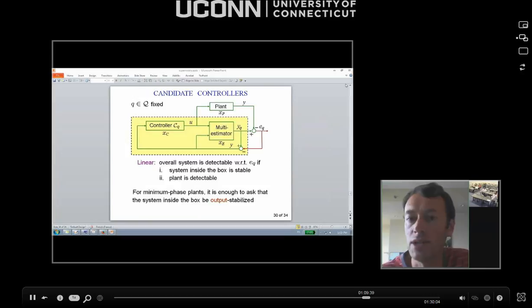And by the way, the detectability is not new, right? If you look at the papers by Steve Morris on adaptive control from the early 1980s, I think he called it tunability or something like that, but essentially detectability is known to be key for traditional adaptive control. So we're not saying anything new in that regard. And whatever control you use, you would need to show that, or if you cannot, then the analysis would need to be changed, because without the detectability property, I don't know how to do the analysis. But with it, I don't care what your favorite controller is, which I think is a good thing about the flexibility of the design.